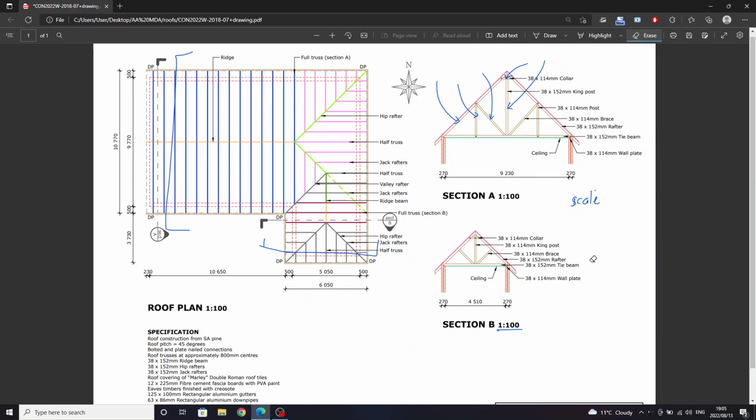So short strut, long strut, king strut, rafter. Same story here. Let's say that's just strut, that's king strut, rafter, collar, collar. For the collar, for the taller, larger truss, I have a value of 12 millimeters, and that corresponds to 1,200 millimeters after you've scaled.